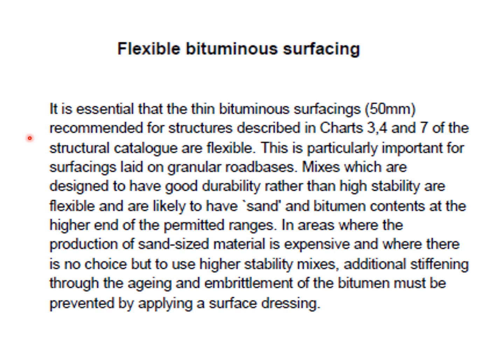We will discuss these charts at the end of this file. This is particularly important for surfacing laid on granular road bases. Mixes which are designed to have good durability rather than high stability are flexible and are likely to have sand and bitumen contents at the higher end of the permitted range.